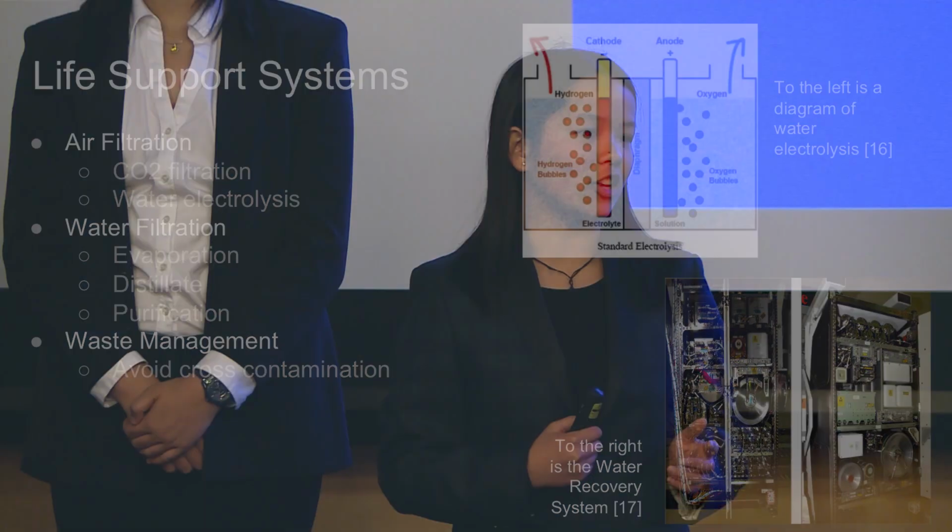In terms of waste management, we would have the crew hand compact any trash that is accumulated on board, duct tape it sealed, and store it in bags. These bags would be put into rigid containers, and these rigid containers would be put in the inflatable module of our space station to prevent cross-contamination between waste and the passengers. Hopefully, then we can put the rigid containers in an empty supply vehicle that will return to Earth and burn in Earth's atmosphere.